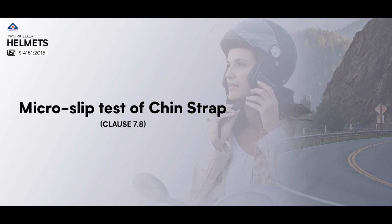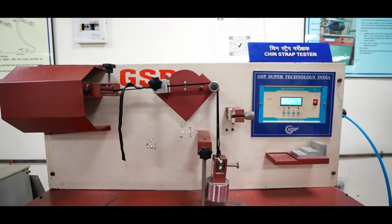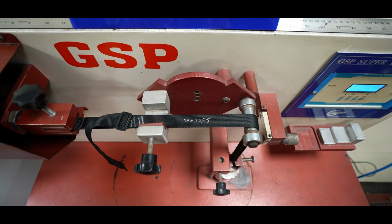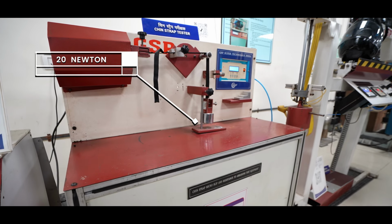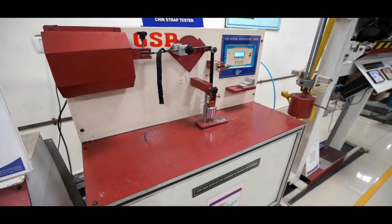Micro-slip test of chin strap, Clause 7.8. The chin strap, along with the tensioning and adjusting device, is subjected to a load of 20 newtons. The load is given a reciprocating horizontal motion with an amplitude of 50 mm for 500 cycles. The total slippage through the grip shall not exceed 10 mm.